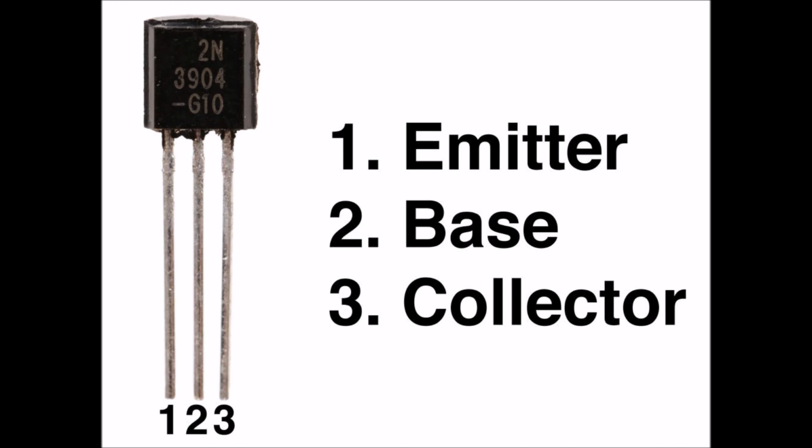In this circuit, the base terminal of the transistor serves as the input, the collector is the output, and the emitter is common to both. For example, it may be tied to ground, reference, or power supply rail, hence its name. The analogous FET field effect transistor circuit is the common source amplifier, and the analogous tube circuit is the common cathode amplifier.